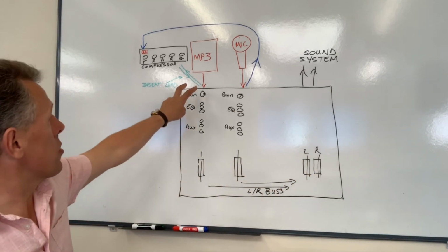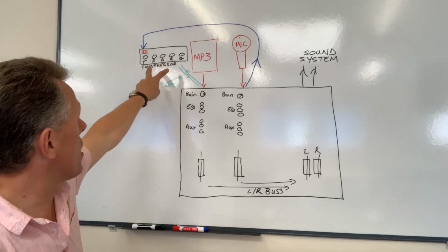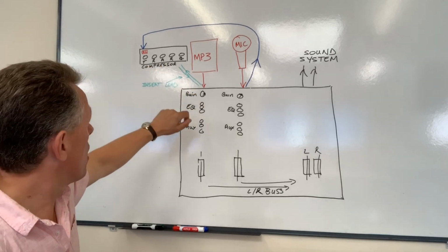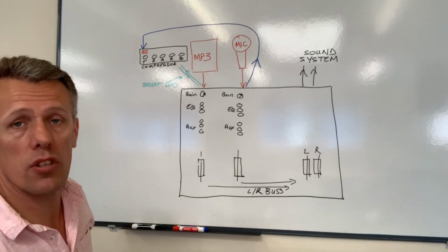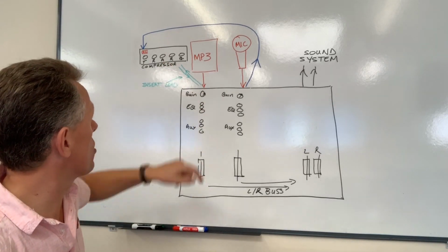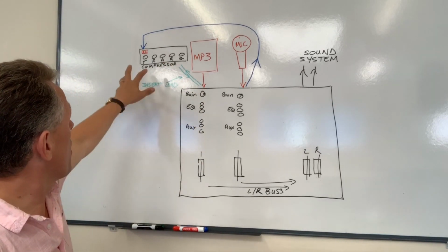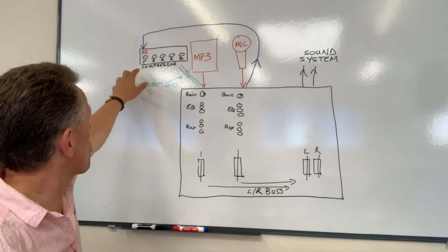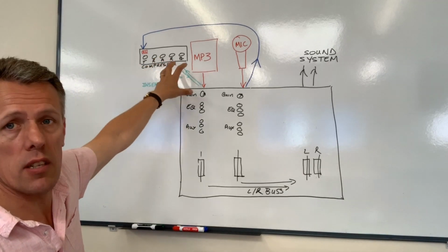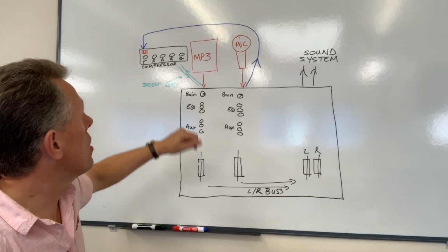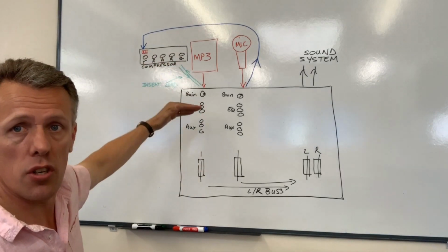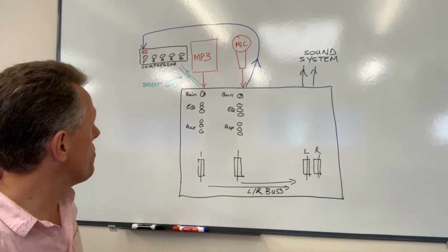Now the audio source is connected to a typical analog compressor using the insert lead, which is a send and return. And then on the compressor, you would set up quite an aggressive compression so that it's actually turning the signal down in volume quite a lot.